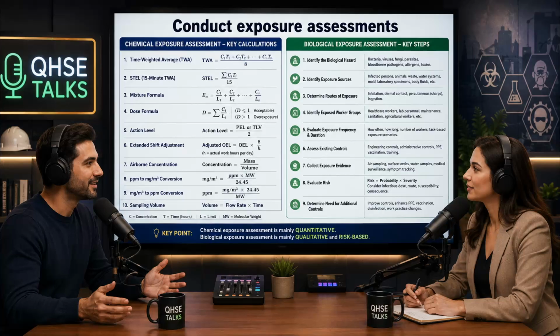And for perchloroethylene, 175 divided by 33 is... All right, I want to pause on that last one. 175 divided by a limit of 33. That single chemical is already massively over its own individual limit before we even finish the mixture math. It is already at 5.30, which means 530% of its allowable dose. The environment is already a catastrophic failure. Yeah, totally failed. But to complete the mixture assessment, we add the fractions. 0.27 plus 0.14 plus 5.30 equals 5.71. Converted to a percentage, the worker's central nervous system is experiencing 571% of the allowable combined toxic dose. It's a severely toxic atmosphere.